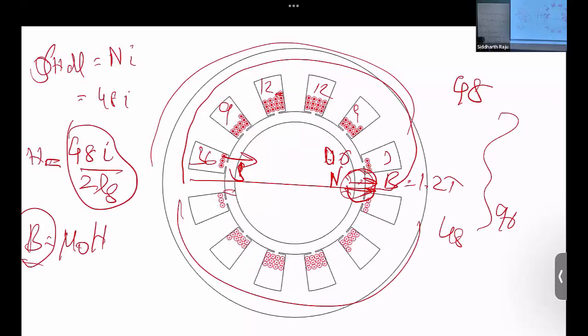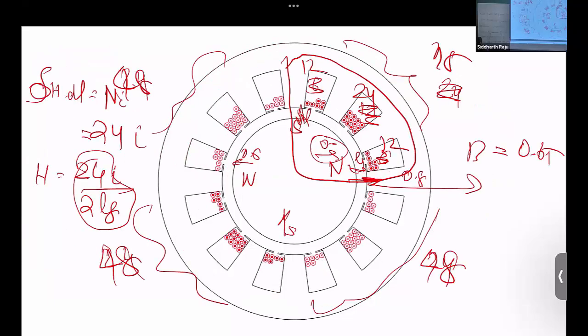But if you go to higher poles, we saw that the B would have dropped down to 0.6. Right here, let's say it goes to 0.8. So your yoke length can be much smaller than what it was before. So you can make either trade-off. You can put in more poles and reduce your yoke thickness and the rotor thickness as well, make your motor smaller, or keep the same motor size, put in more conductors and increase your torque in the motor, right? With that, let's call it a day and we'll continue next week.